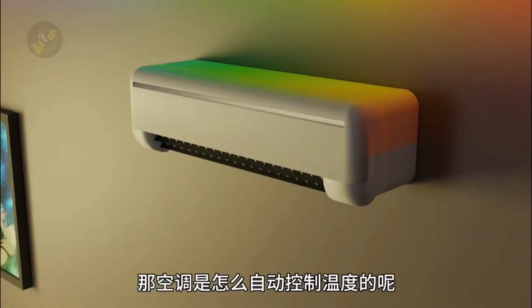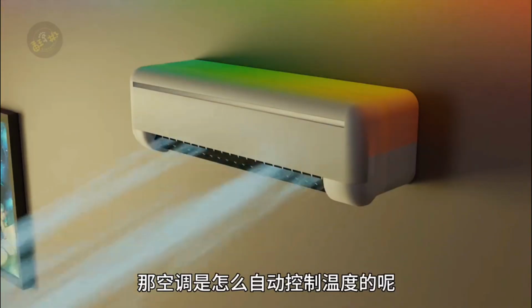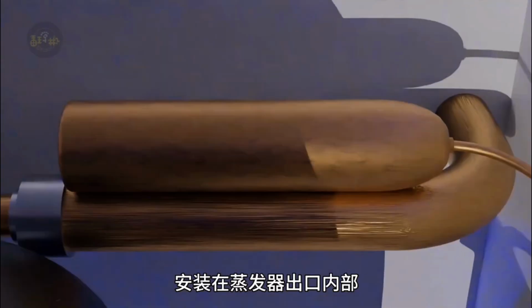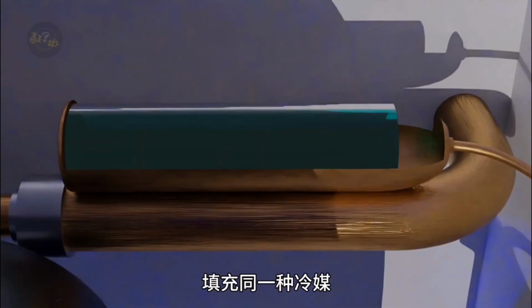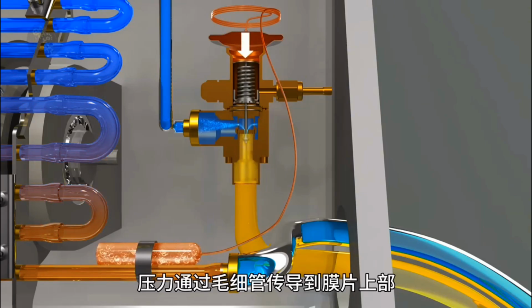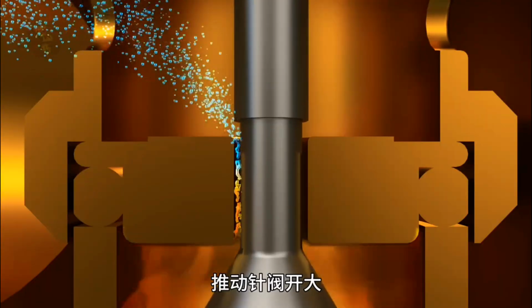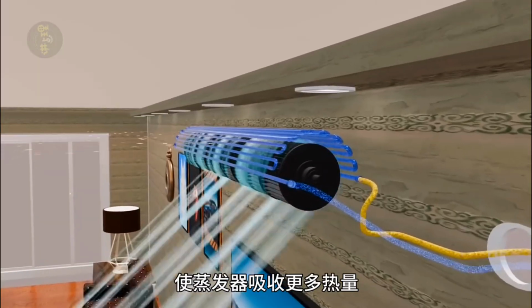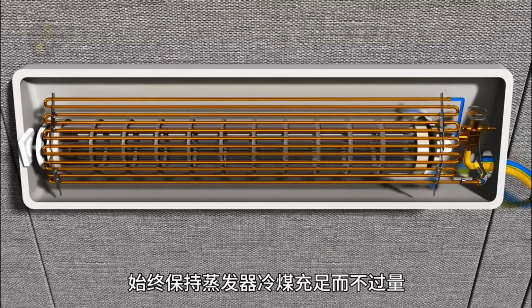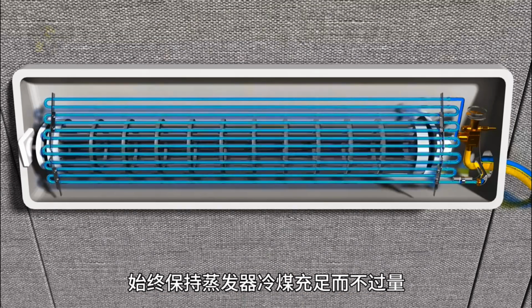So how does the air conditioner automatically control the temperature? This brings us back to the thermal expansion valve, which has a temperature sensing bulb installed at the evaporator outlet, filled with the same refrigerant. If the outlet temperature rises, the refrigerant in the sensing bulb vaporizes, causing the pressure to increase. The pressure is transmitted through the capillary tube to the top of the diaphragm, which will move downward. The pressure pushes the needle valve to open wider, thereby increasing the flow of the refrigerant, allowing the evaporator to absorb more heat. Conversely, the opposite is true. This forms a dynamic closed-loop control system, always keeping the evaporator sufficiently supplied with refrigerant without excess.